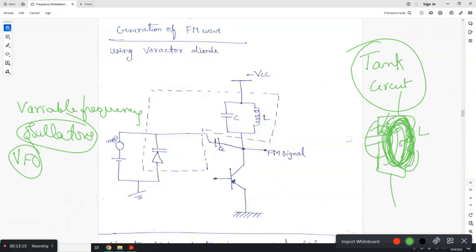And what does it generate in the process of charging and discharging? Charge, discharge, charge, discharge. What will continue? It will generate an oscillation. There are also things called damped oscillations and undamped oscillations. So the LC circuit, which is called a tank circuit, generates oscillation, which is called an oscillator. This is the simplest circuit which generates oscillations. Have you understood how it generates oscillation?